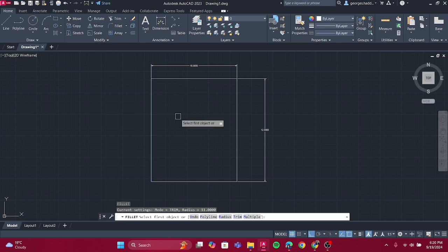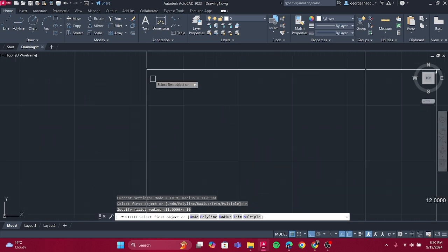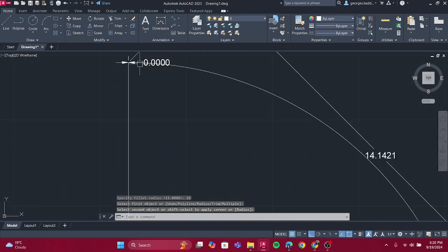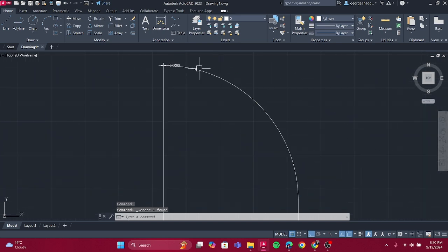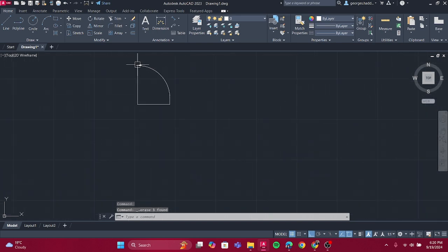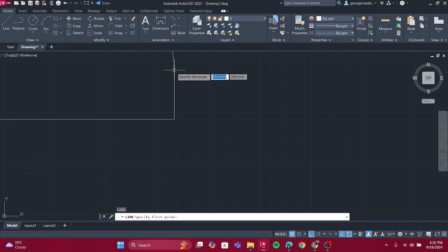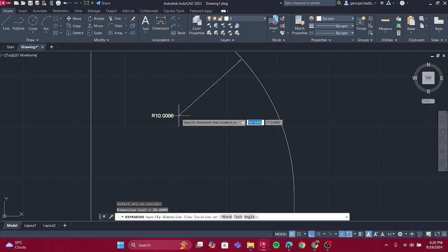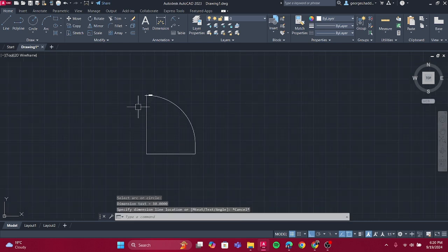If I select a radius of 10, it will, because it will start right from the edge of the box, from here to, in this case, from over here. As you can see, delete this. As you can see, it starts from right there, from the very edge. Over here, you will still have a distance of 2 left. And to double check, you can see the radius of the circle, which is a 10. Be careful of these mistakes and use Chamfer and Fillet to boost up your drawings and be more efficient and have more flair to them.